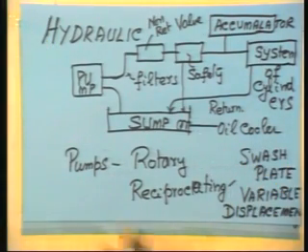When oil is working in a closed loop, circulating inside a closed loop, it tends to heat up. The pump is putting in some energy and it tends to heat up. There will be friction in the cylinders, that will generate some heat. The oil will tend to heat up. That heat has to be extracted. So there is an oil cooler in the sump.